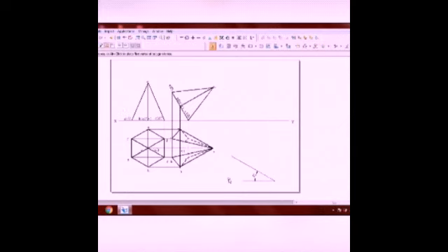select as usual the second top view, of course along with the ABCD letters. And the most important thing is you have to hold the corner of the edge on which it is resting. The intersection symbol will indicate that you are holding the proper corner. Then shift it. Of course, you have to switch on the multiple view. Place that corner exactly on the line.